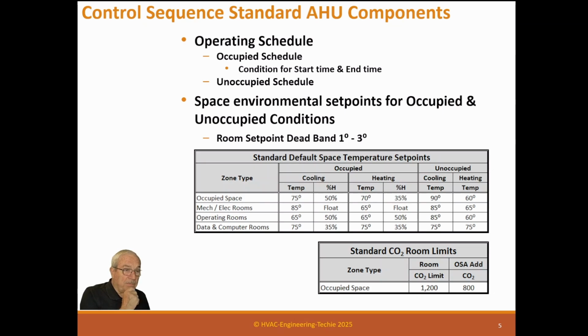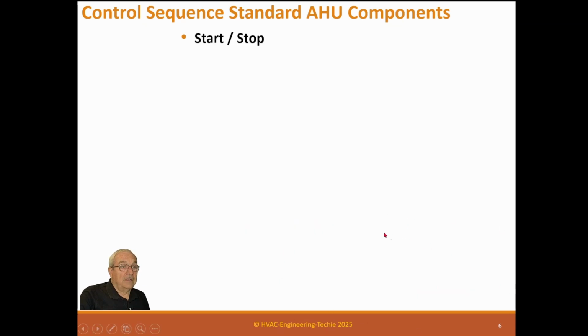And that's, I think, by people who believe that CO2 is a pollutant. And, of course, it's not. It's one of the gases we need to survive. 900 is not a problem. 1,200 is not a problem. Actually, we've measured in classroom settings up to 3,500 with really no ill effect. So this 1,200 parts per million is not that bad, and you should use that if you're trying to use energy efficiency. 900 you could use, but you're going to be spending a lot of money for it.